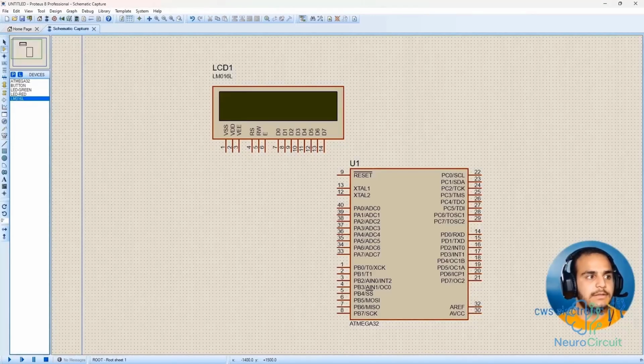For the moment, it doesn't really matter precisely why they're named the specific way they are. It's simply very good to begin to get thoroughly familiar with them and their functions. Because in the software, we assign the pins using these names, and the standard way these data pins are connected in CodeVision is that it uses these 3 and the last 4 pins.